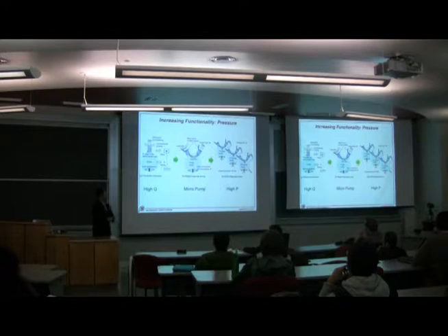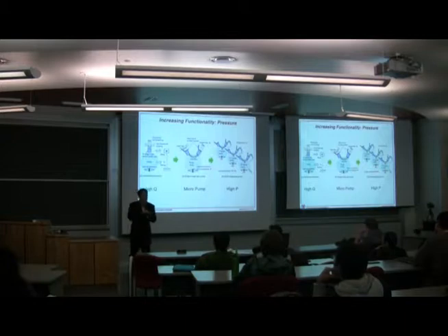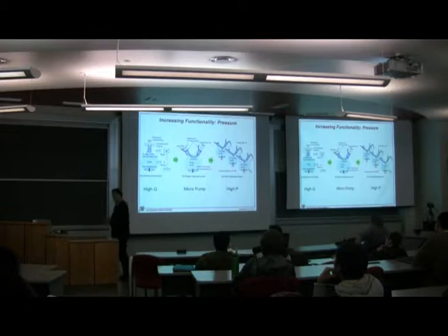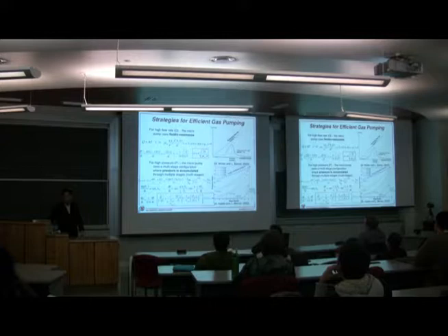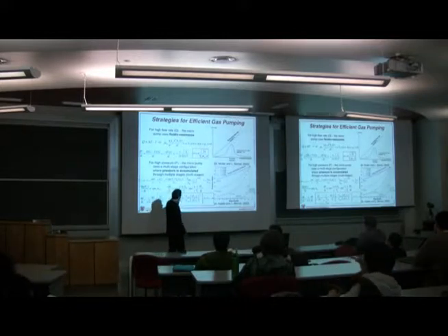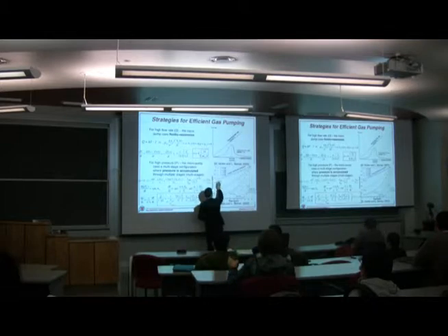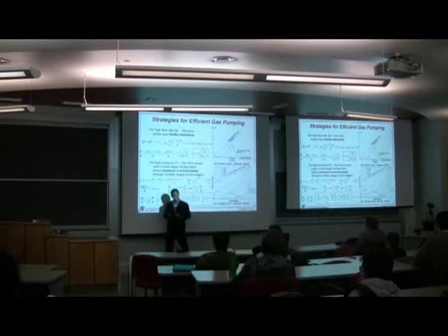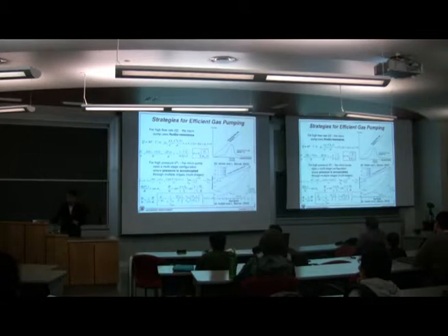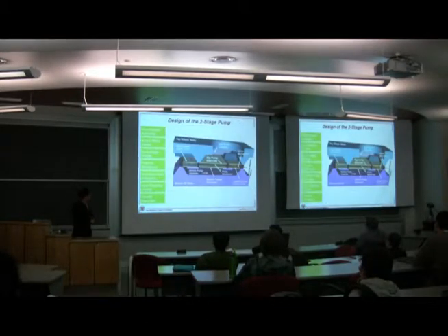And then, of course, to push air through these little chips in the micro domain, you need very high pressure. Just the flow is not enough. You have to generate high pressure. So how to do it? We just connected them in series, in short. Of course, a PhD is not just such a simple thought, right? A lot of modeling tells us there has to be a certain design criterion, which is called the compression ratio. And so we built a micro device just like this.